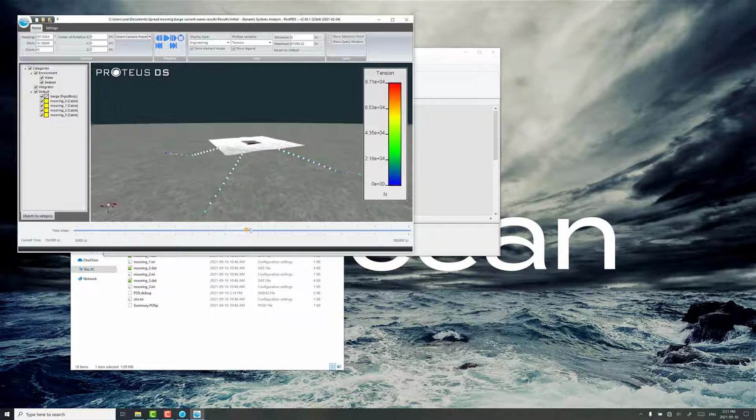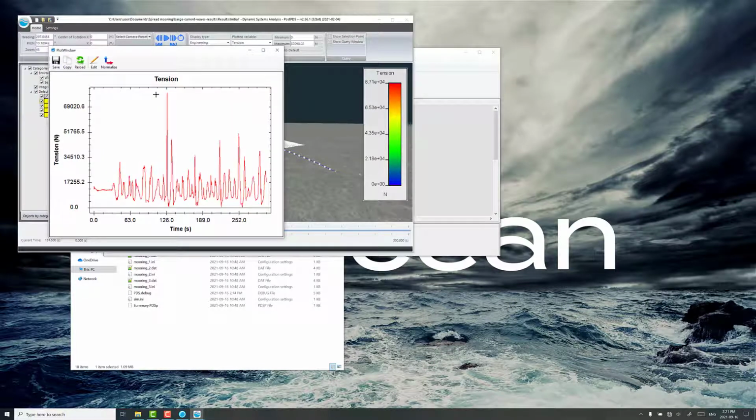There's some big dynamic loads happening here and there. Can keep an eyeball on them with the tension plot. A couple of big peak loads here, so it's good to try a bit longer of a simulation and see what's happening. Just try a few different simulations that are set up the same, but with a different wave seed to see what the peak loads look like.